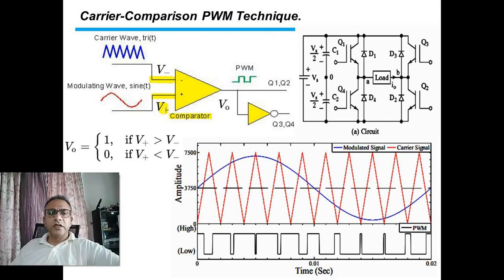By tradition, the comparator has two inputs, the inverting input and the non-inverting input, V minus, V positive. These are just simple labels. There is no restriction of voltage polarity. We can supply positive or negative to either input. So if we are dealing with V positive, it doesn't matter if we give a negative input or the positive input.